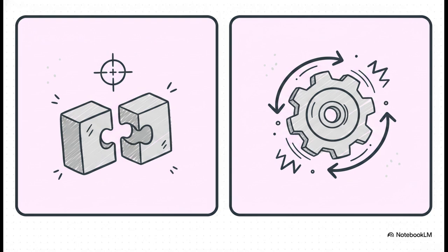Let's look at another fundamental comparison, true position versus circular runout. True position is fundamentally a locational control. It defines how much a feature's static position can vary from its intended perfect coordinate, often using the location of other features to set relative controls. Circular runout, on the flip side, is a dynamic, rotational control measuring surface deviation during active rotation.